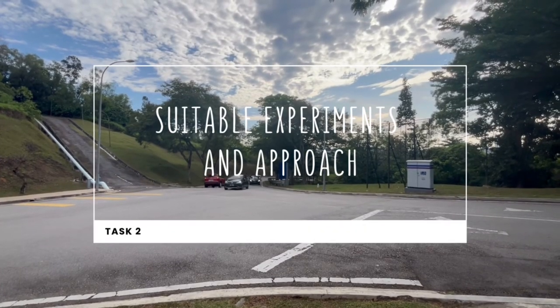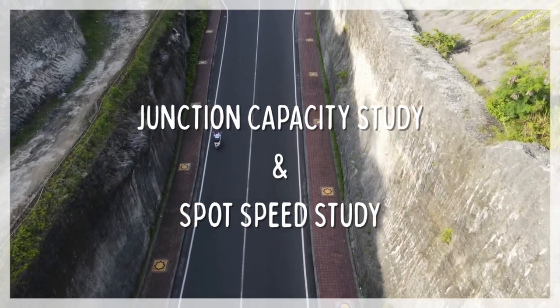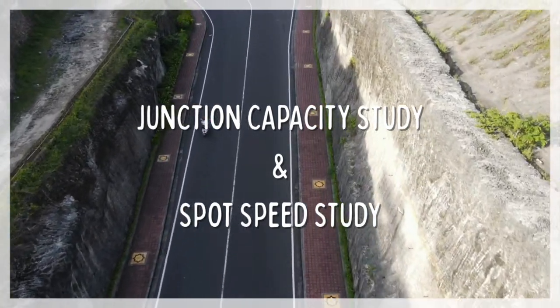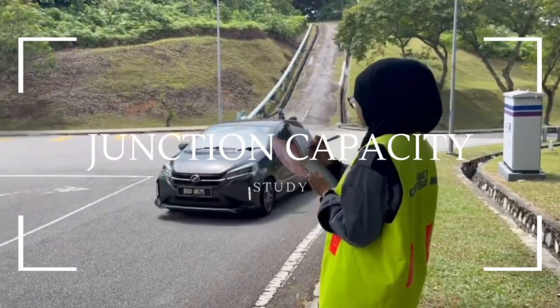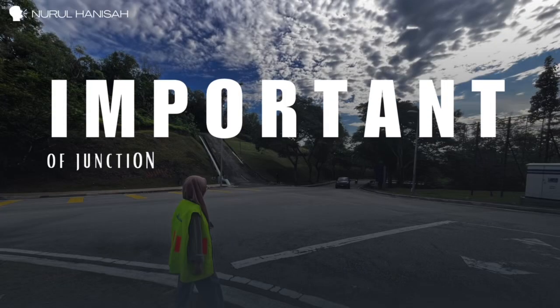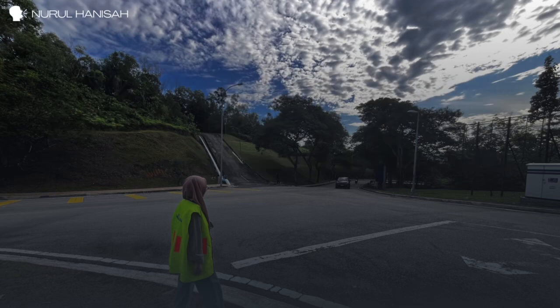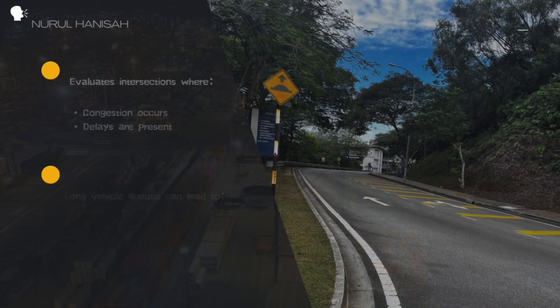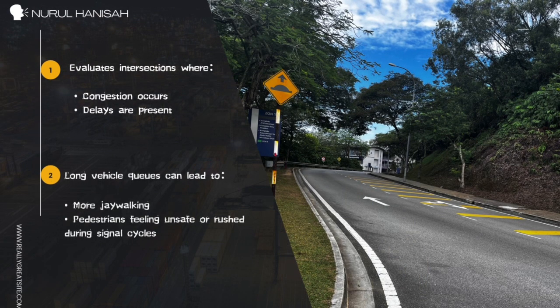Suitable experiments and approach. The methods that we use to justify the road safety at this site are spot speed and junction capacity study at peak hours to define the worst case scenario. Junction capacity study. Junction capacity study helps in evaluating traffic flow by determining level of service and to justify safety improvement. In addition, it helps to determine whether pedestrian crossing phases are needed.